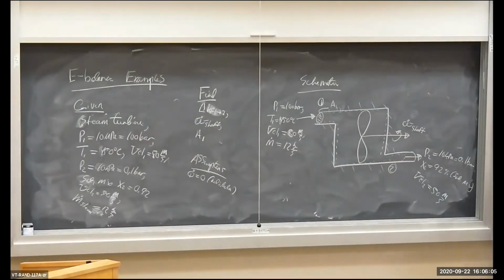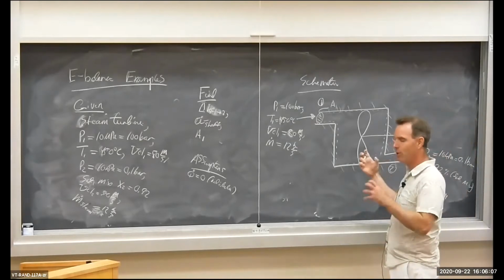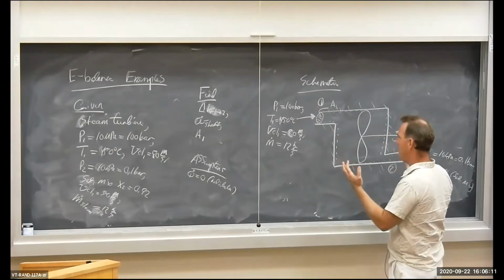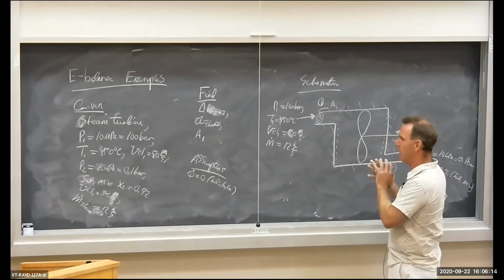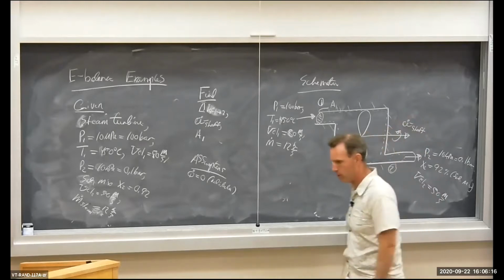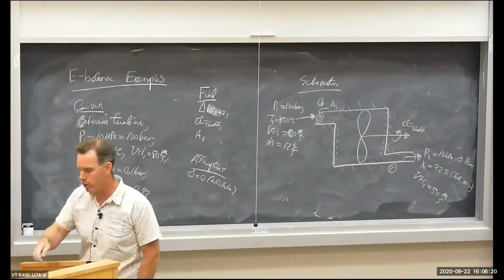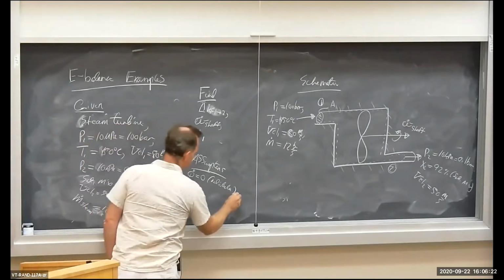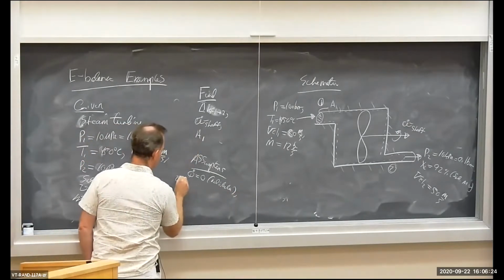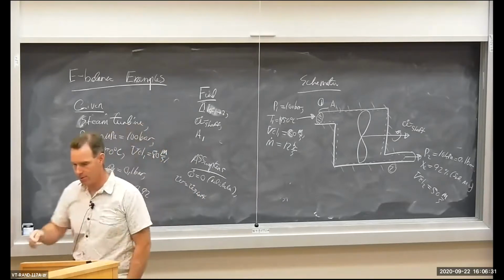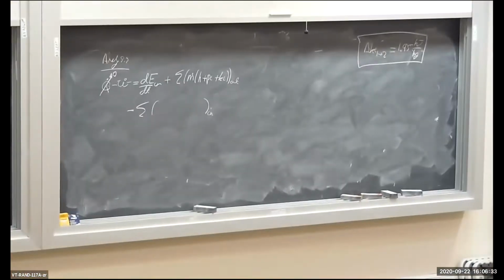And I'm assuming that the turbine itself is not changing shape. The casing is remaining intact, and the control volume is not changing its volume, getting bigger, or being distorted. So I'm going to assume that W dot is equal to W dot shaft. No boundary, no electric work.